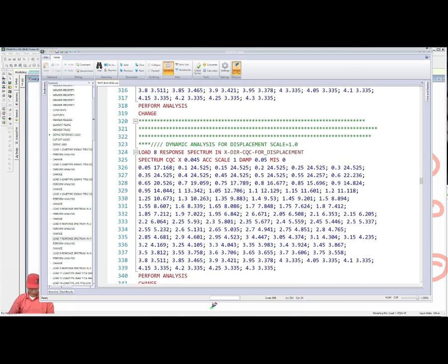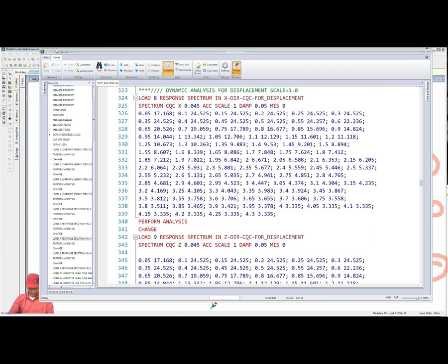Load cases 8 and 9 we shall not scale. We shall use these load cases for generation in the combination of serviceability load cases, because the code doesn't require the displacement estimate to be scaled up. So let us now save the STAAD Pro input editor.